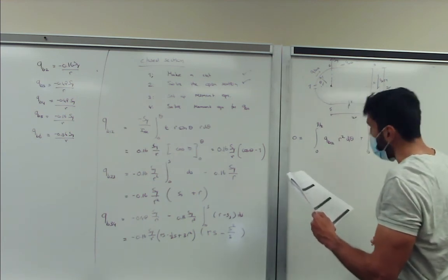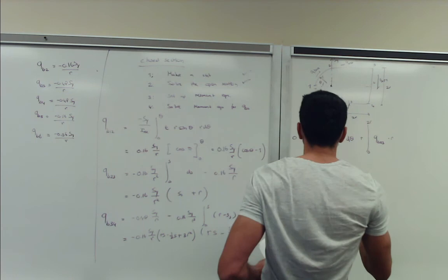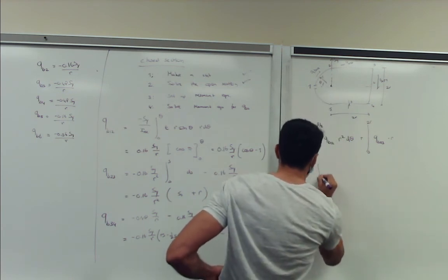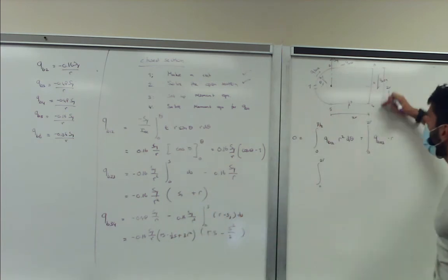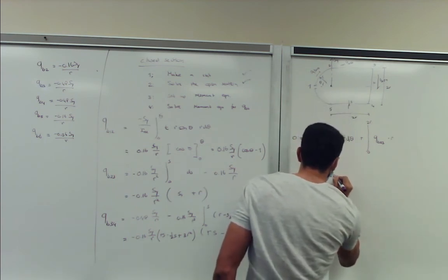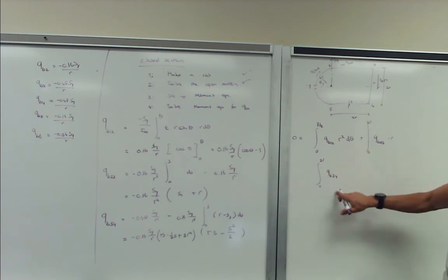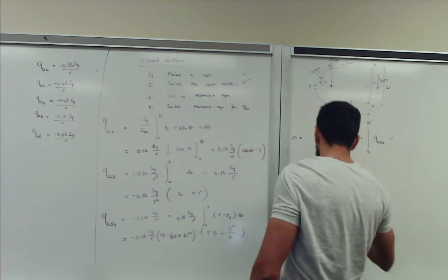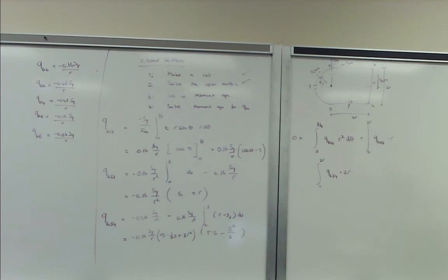And then we also take the integral of 0 to 2R. That's how QB34 travels, the total distance. So again, QB34. We went from shear flow, we integrate over the distance it travels to get shear force, and we multiply by the moment arm, in this case equal to 2R, and we get that moment contribution. So is that an added or a separate equation? Oh, no, this is added, sorry.